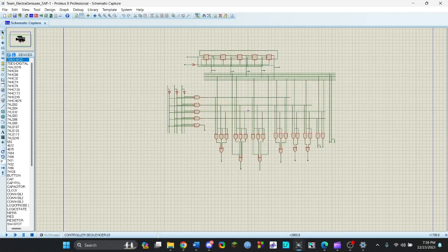Instructions sent to each component are of 6 bits because it is our 6-bit computer, so everything will be 6-bit. The first 3 bits of these 6 bits are called the opcodes, and these opcodes define what type of instruction the component has to do. The last 3 bits, or the lower 3 bits, pass parameters such as the address field in the instruction.